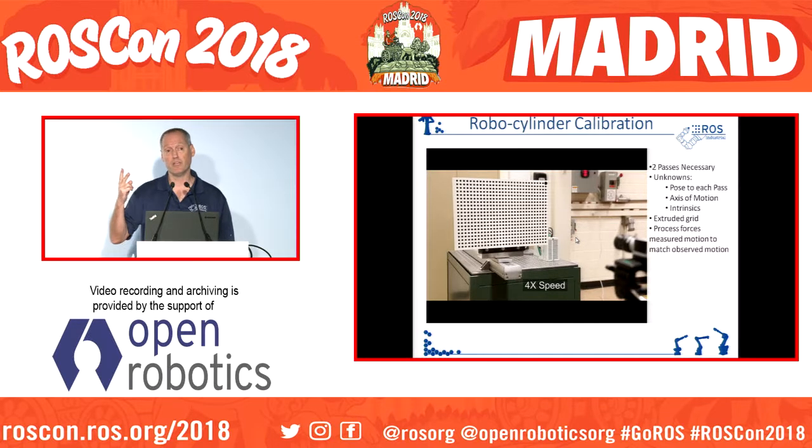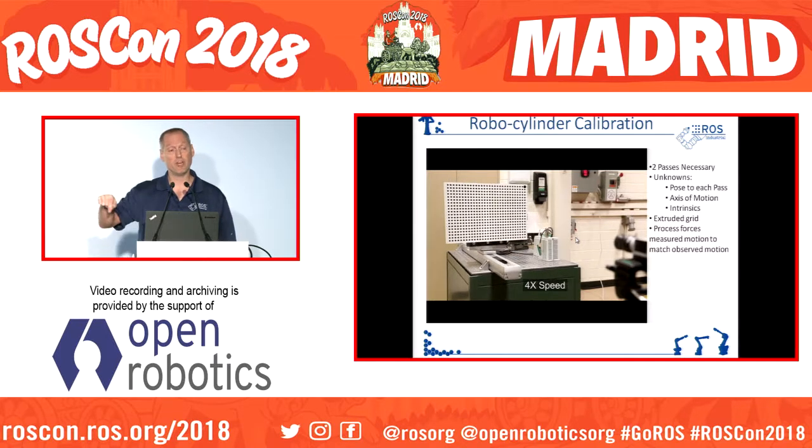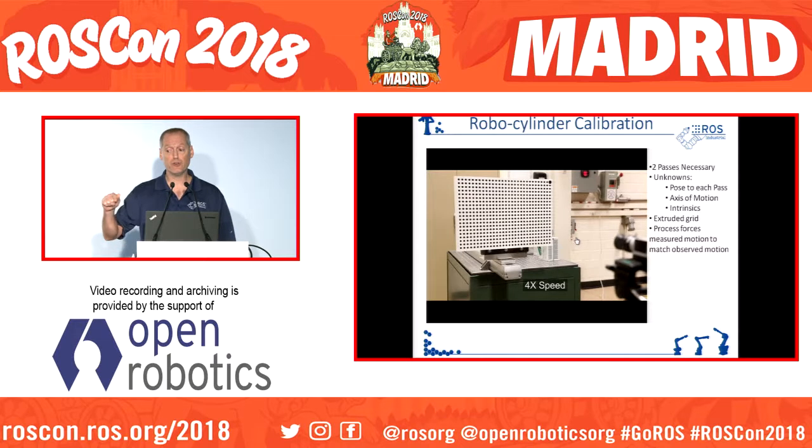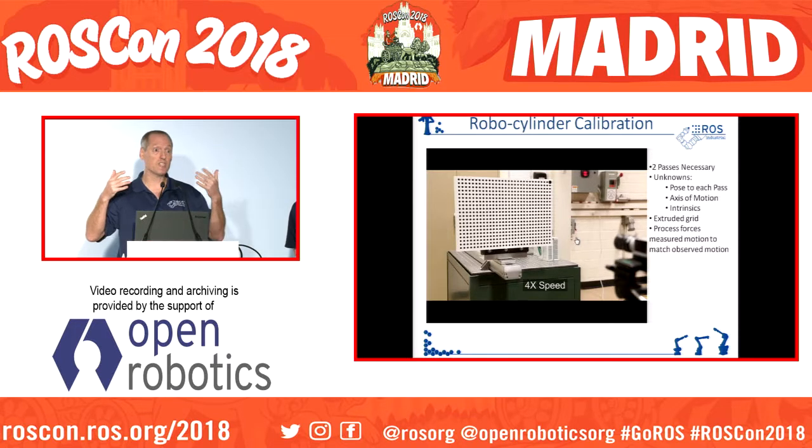So we're only computing two different poses, the pose between the camera and the starting point in each case, and then the axis along which that rail moves in the target's frame. And if we do those two, we get very good intrinsic calibration consistency. And essentially think of that as a sort of a frustum of data going back into space. So we're seeing it's almost like a single target that has a lot of data.